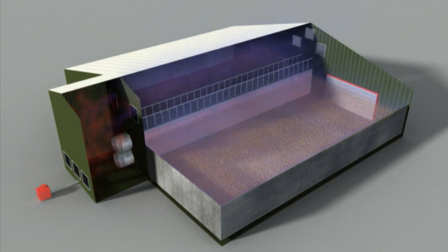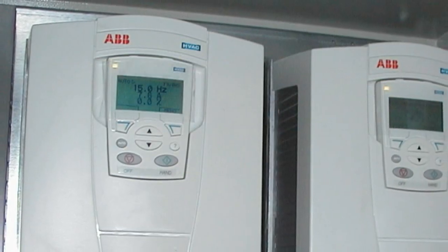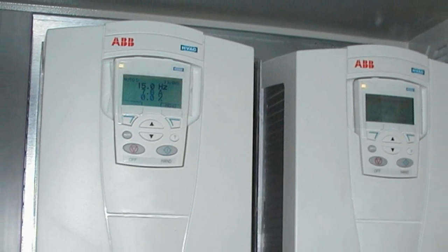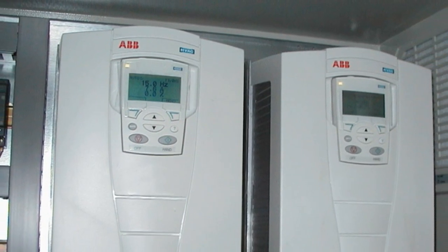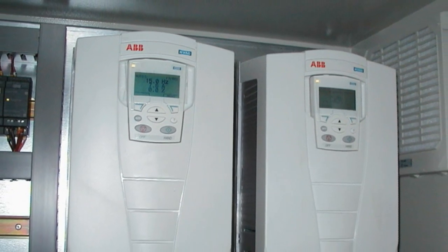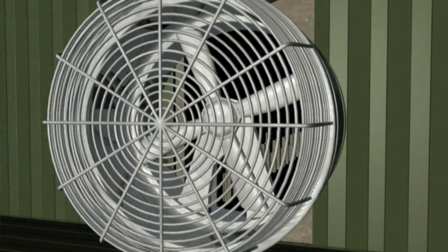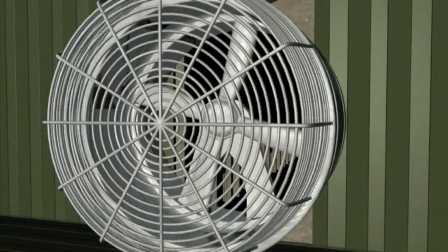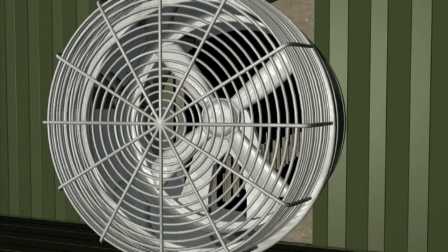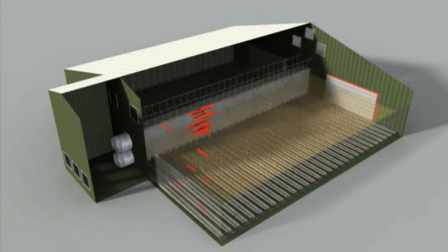In order for fans to safely transport fog, a more gentle action is needed. This is accomplished by installation of a variable frequency drive, which allows the fan speed to be adjusted. With the fan running at low speed, it is safe to use to deliver fog directly to the crop and manage its distribution around the store.